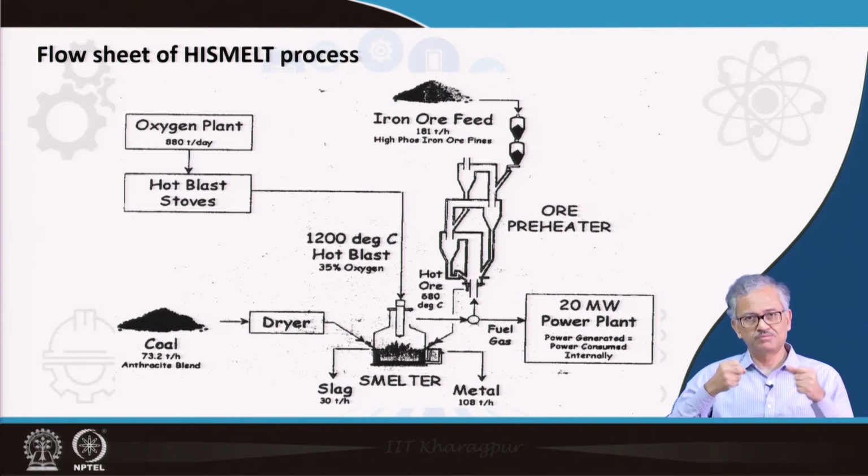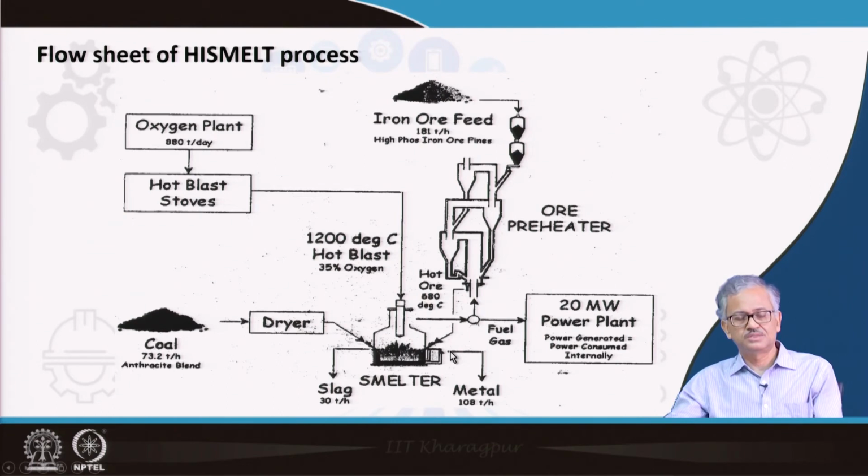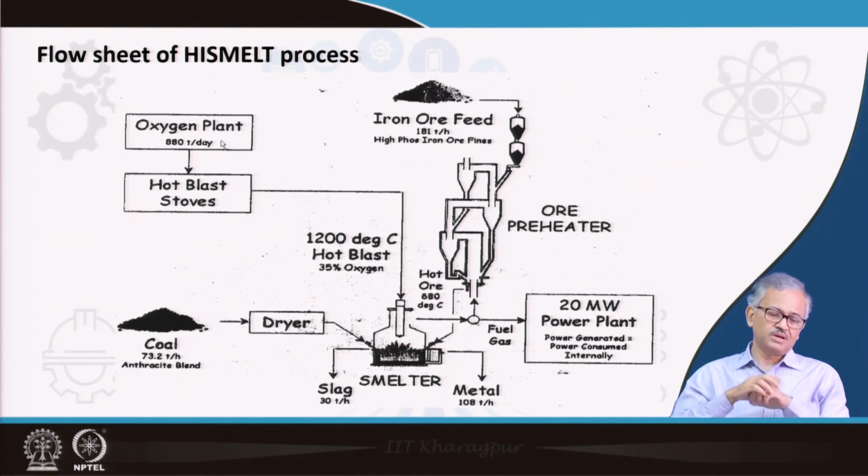Melting of the iron ore becomes faster, and then coal gasification and the coal oxidation also become faster. Okay. So that basically the process becomes efficient, your coal also decreases. Also the preheated air blast, that also decreases coal. And also you do not have to use a large amount of oxygen. So the oxygen plant will only be for enrichment purpose.